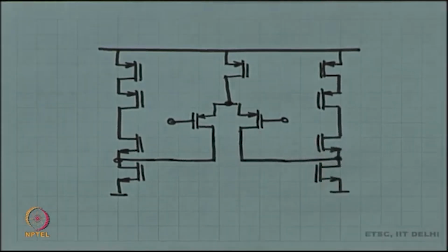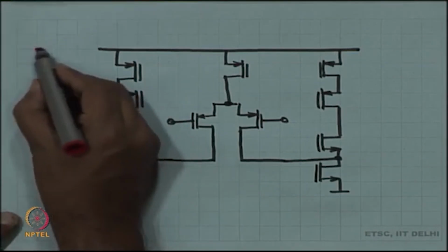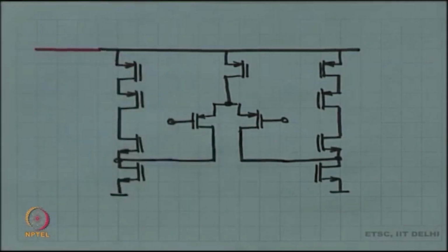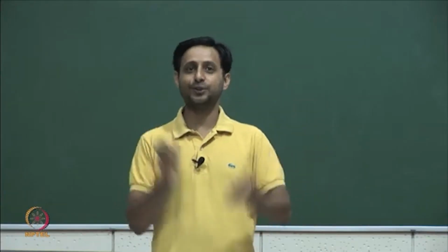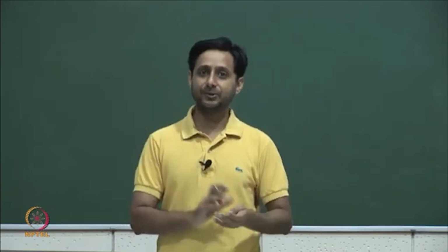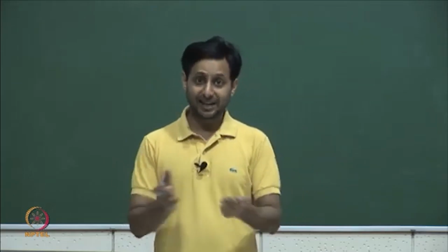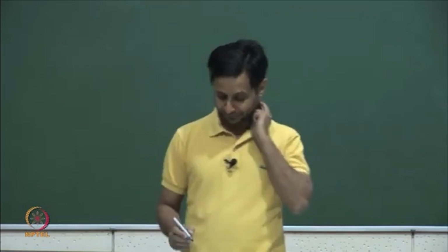All right. So, this is my structure, and now I have to work out all these individual gate voltages. Okay. So, let us take out a reference current. We always start with a reference current. What is inside this reference current? It is one of those constant GM reference current sources. Okay. So, that is how you are going to make that reference current.